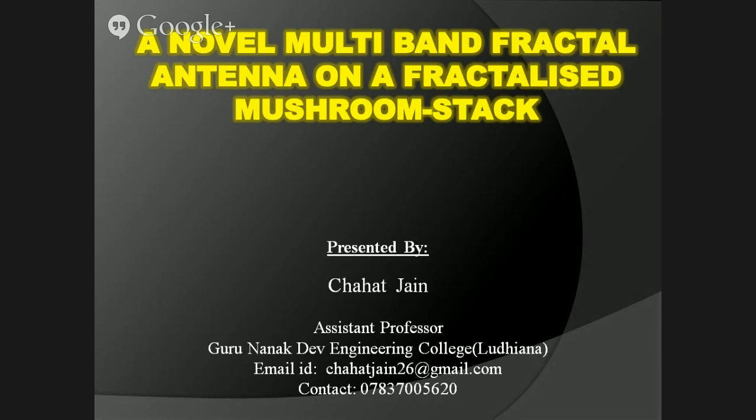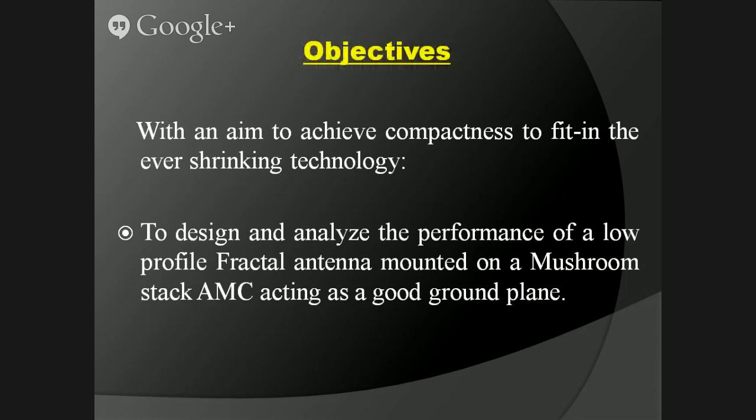For starting this project, a few things were in my mind. First, the complexity of the structure should be less. There should be a reduction in the metal, that is, cost reduction, and the same antenna could be used for more than a single operation. So, with an aim to achieve compactness to fit in the ever-shrinking technology, the objective was set to design and analyze the performance of a low-profile fractal antenna mounted on a mushroom stack AMC, which will act as a very good ground plane.